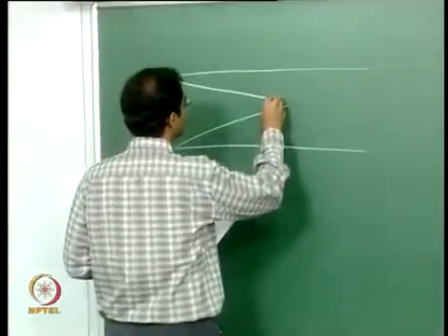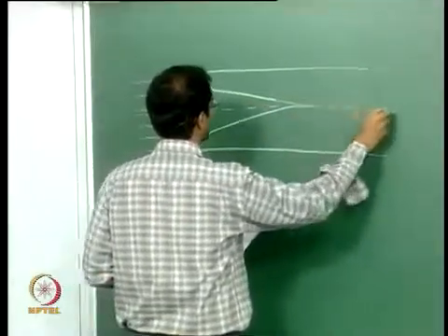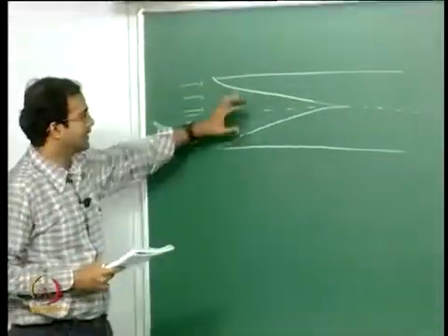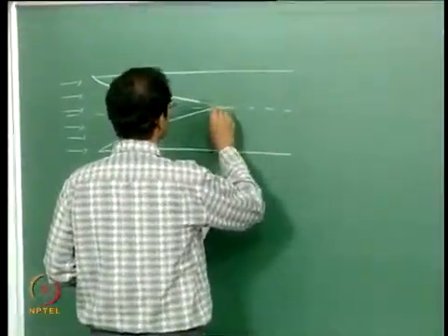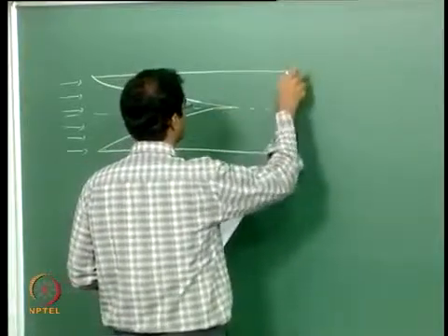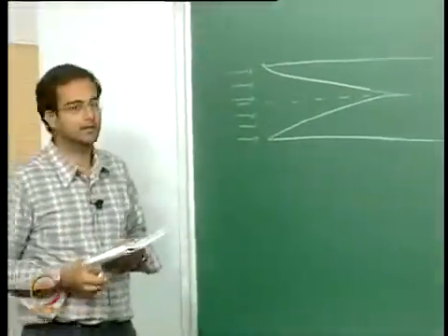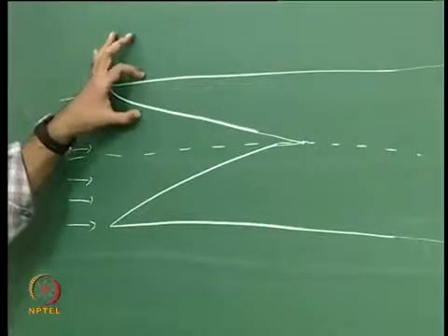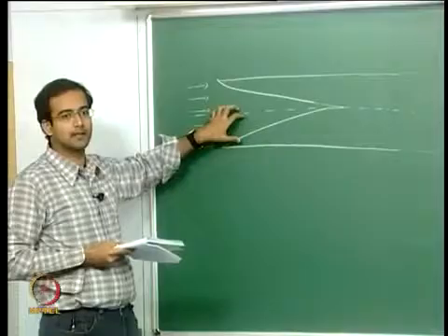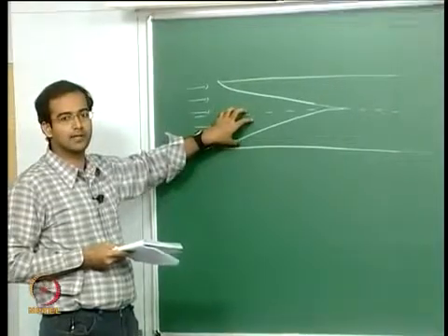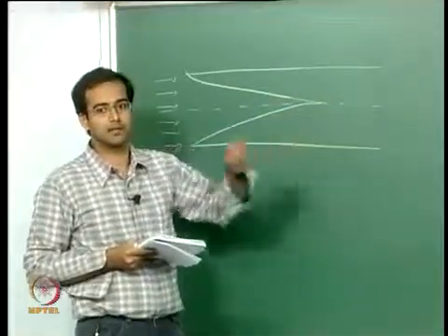and this growth keeps going on till a particular location which is at the center of the duct. Exactly at the center the two boundary layers will merge, and after that the region you are looking at here is completely dominated by viscous effects. Whereas at the inlet you have a very small region close to the plates where viscous effects are important, and outside the potential inviscid flow theory is still valid, once the two boundary layers merge, in this region everything is viscous dominated.